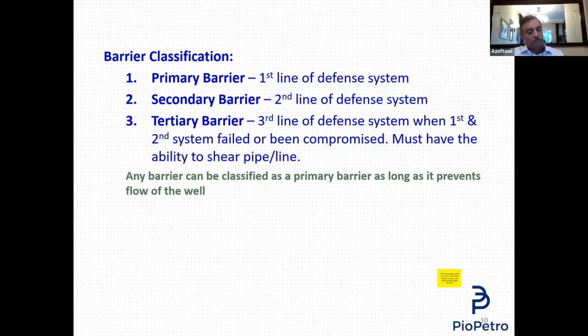I said, no. If you remember, I believe last time I said, this difference between 5,000 psi and 7,500 is not for you to use in the operation. This is to save your life, in case of emergency. Do not ever use it in operation. This BOP is rated for 5,000 psi. Never use it above 5,000 psi.